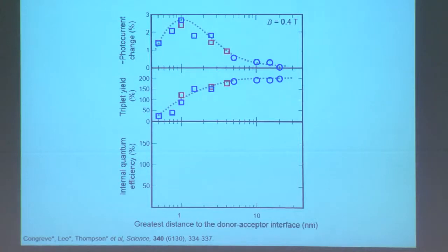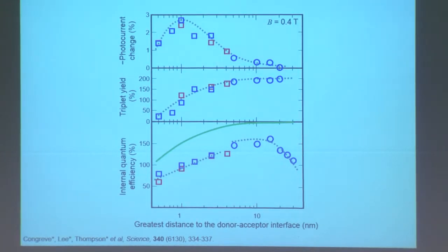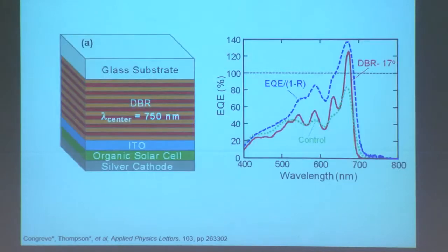effective fission. And we can further take this and turn this into an internal quantum efficiency. We can build a ceiling here just by assuming you collect everything. And then when we look at our devices, we see a curve that looks something like this. You lose about 40 points of internal quantum efficiency, but in general, you trace this curve, so we can see that singlet fission really is driving the physics in this device. And this tail off over here is due to diffusion losses, with excitons not being able to reach the interface anymore.